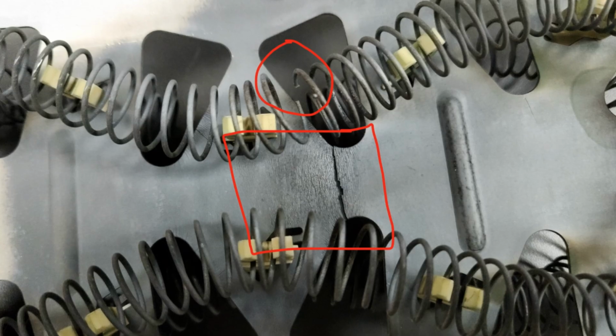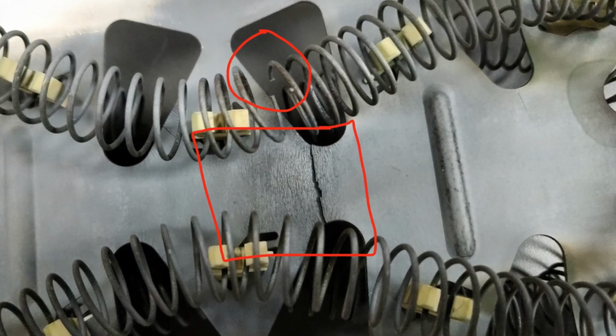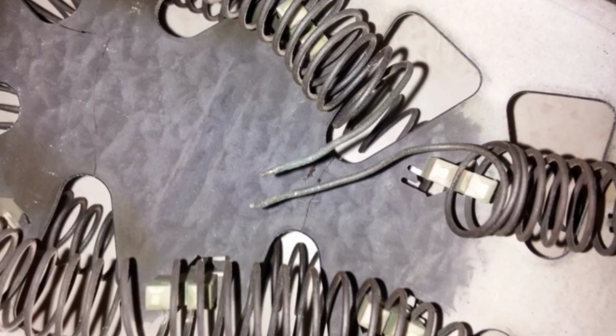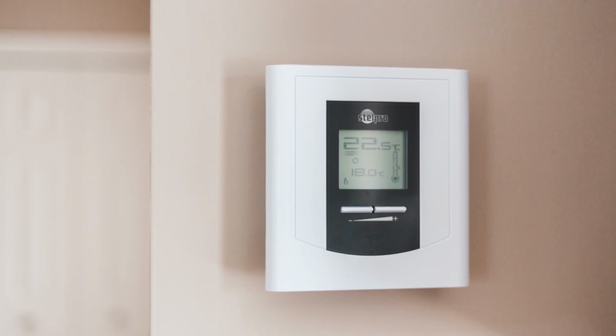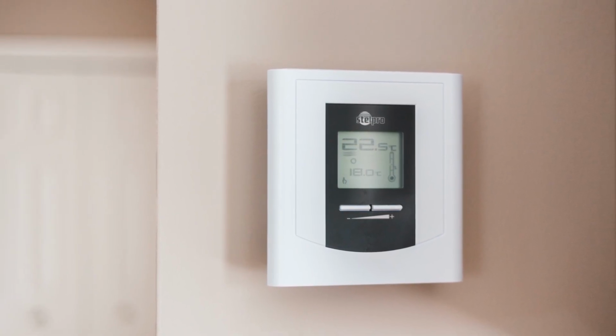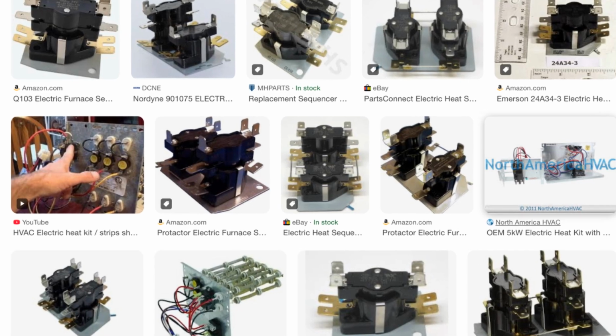Heating elements fail for several reasons. The coil can break, connections can loosen and create hot spots. The metal can fatigue over time, and long periods of heat stress can burn the element open. When an element fails, the symptoms are simple. The heat feels weak. The system runs much longer. Only part of the home warms up, or the blower runs, but the air is not warm.